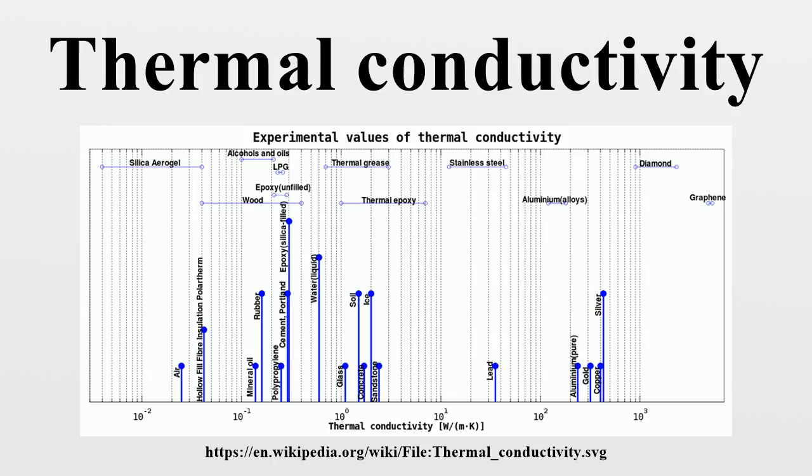Magnetic field. The influence of magnetic fields on thermal conductivity is known as the Righi-Leduc effect. Convection. Air and other gases are generally good insulators, in the absence of convection. Therefore, many insulating materials function simply by having a large number of gas-filled pockets which prevent large-scale convection. Examples of these include expanded and extruded polystyrene and silica aerogel, as well as warm clothes. Natural, biological insulators such as fur and feathers achieve similar effects by dramatically inhibiting convection of air or water near an animal's skin. Light gases, such as hydrogen and helium, typically have high thermal conductivity.